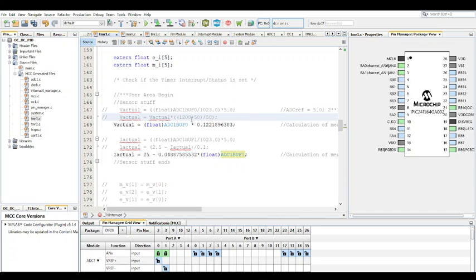Basically what you have here is the bigger resistor plus the smaller resistor, divided by the smaller resistor. You multiply that by the voltage that you got. If you do all of that, basically 5 divided by 1023 multiplied by this right here, you get this here. I don't include these two lines in the code. I commented them out for code execution time, because this is almost like a digital control loop.